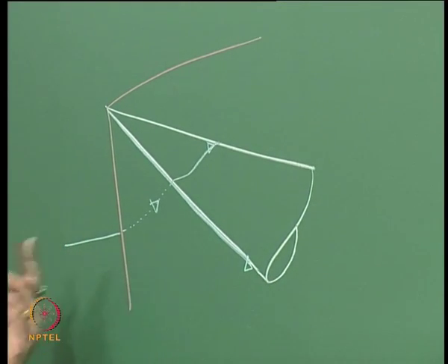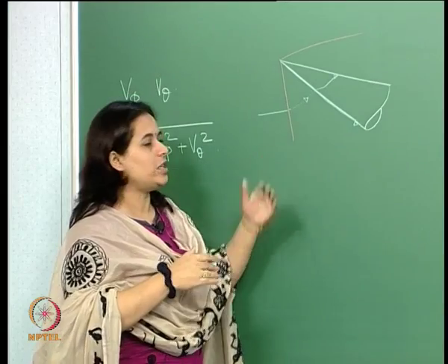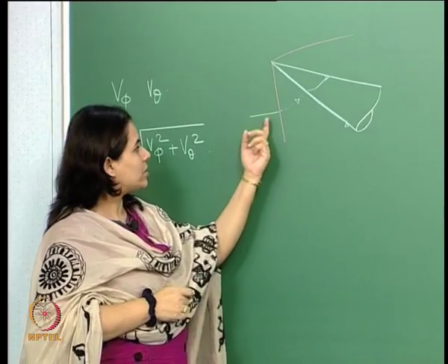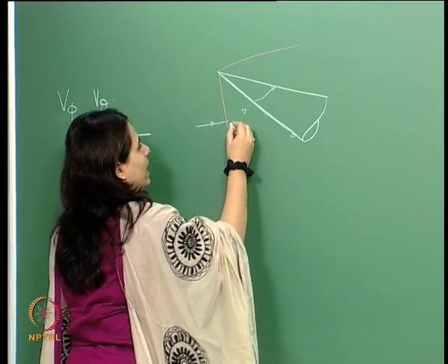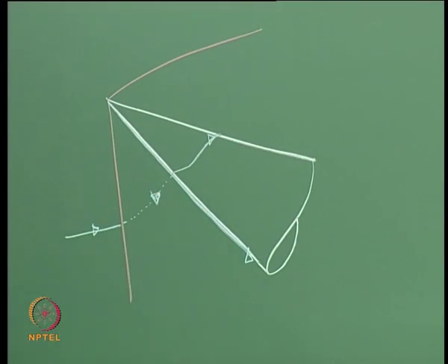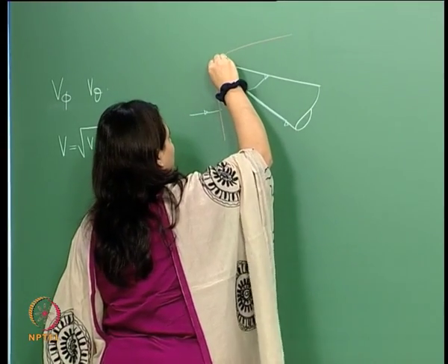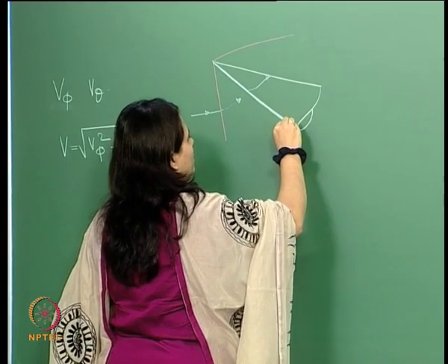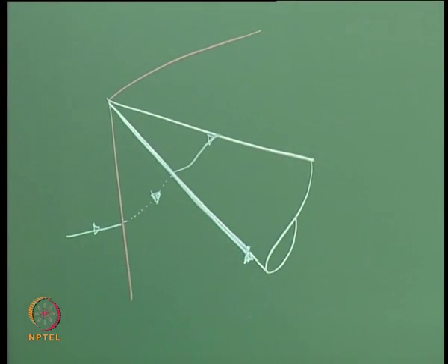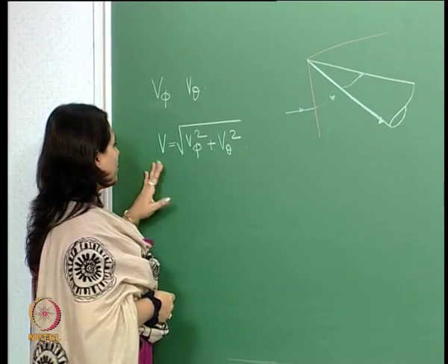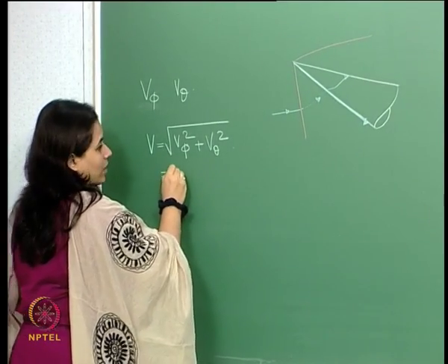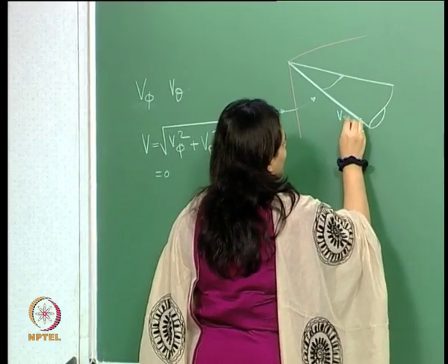So, it is curling up, it is changing its phi, it is changing its theta. This streamline, for example, definitely has a finite velocity here. But look at this streamline. It is not curling up, it is just going straight onto the surface of the cone, moving along it, and it does not change its theta or its phi. So v theta and v phi are 0, which means this velocity here is 0.